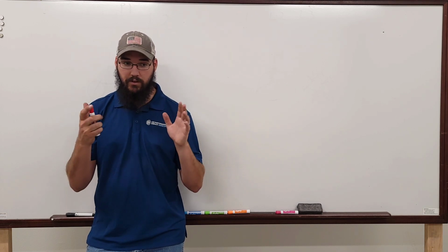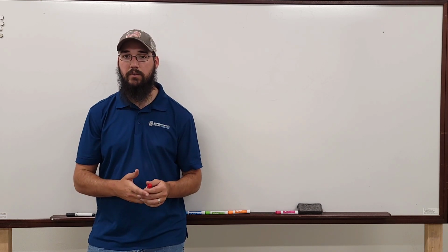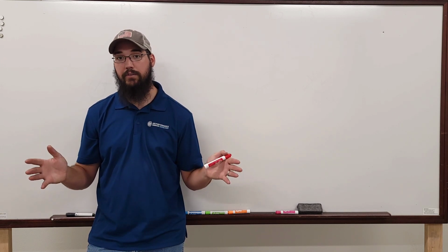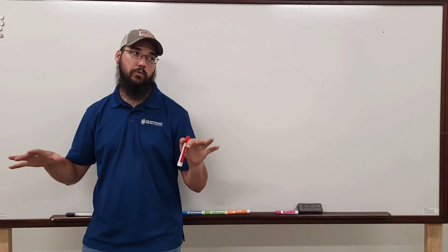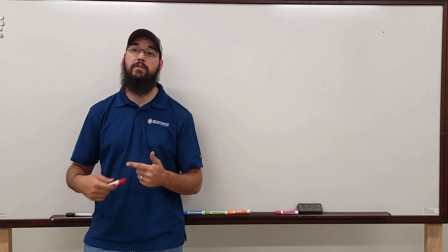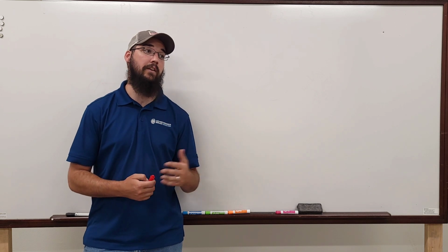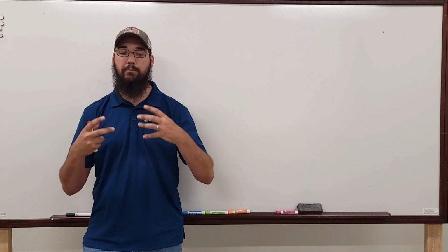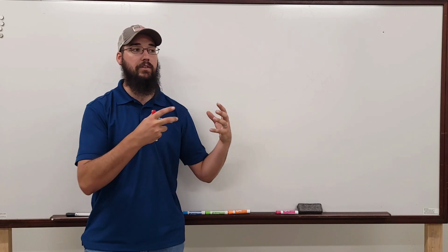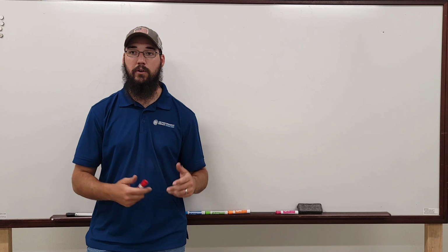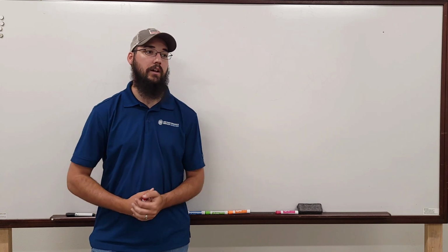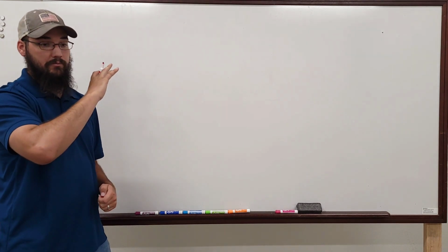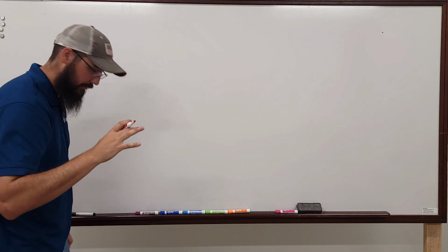So this has a direct correlation to the motor, because this is where we start getting into centrifugal theory and lift. Okay, I'm not going to try to go too deep into the science of this, but I want to give you some understanding. The whole point of this class is to give you some understanding of the motor and how we can properly take care of, utilize, and protect these motors from abuse, and from an efficiency standpoint. Lift is literally, we can calculate compressor lift in a refrigerant system.